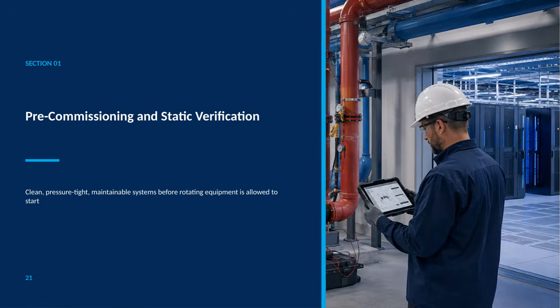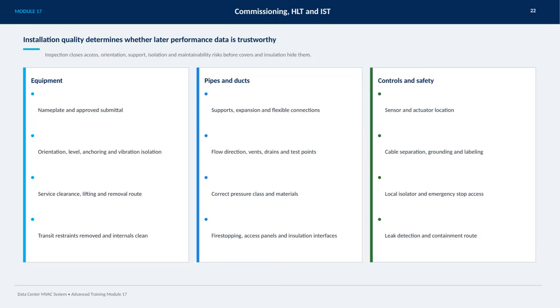Here we're focusing on Section 01, which covers pre-commissioning and static verification. This phase is all about ensuring that the systems are clean, pressure-tight, and maintainable before any rotating equipment is allowed to start. Getting this right is crucial because it sets the foundation for safe and efficient operation down the line. It helps prevent issues that could arise from contaminants or leaks and ensures everything is in proper working order before moving forward. This slide emphasizes that installation quality is the foundation for reliable performance data later on.